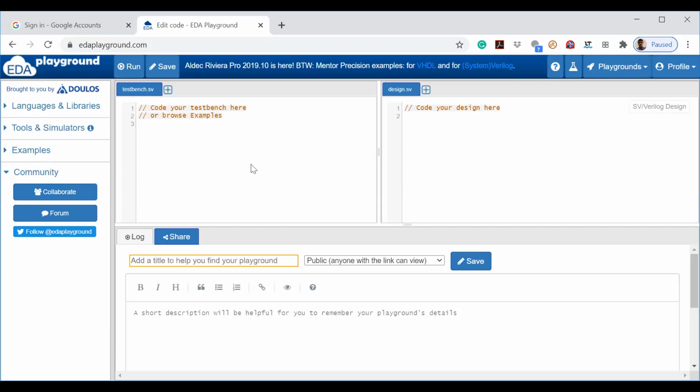We shall apply some standard test input, and after simulation the waveform will come, and we shall check the output in terms of waveform. Now check for different inputs whether you are getting the correct output or not. So the function of the test bench is to test your design. Your actual digital system will be implemented in the design, but in the test bench you are going to test your design.